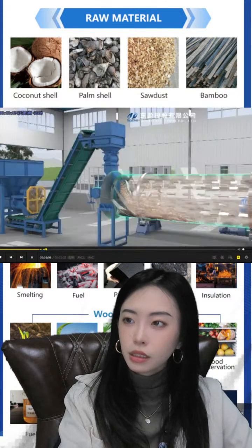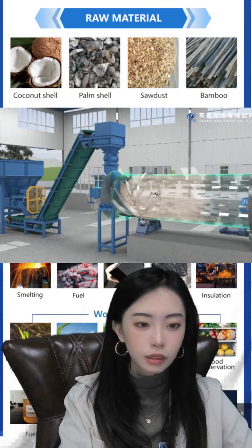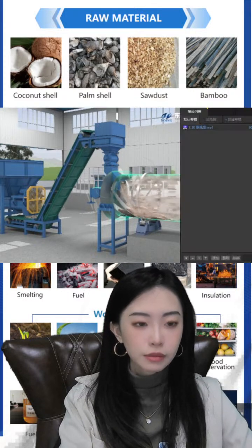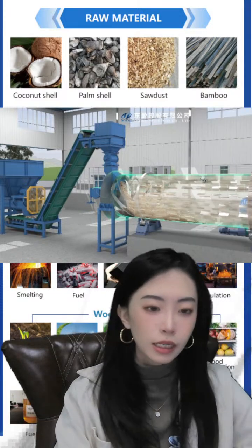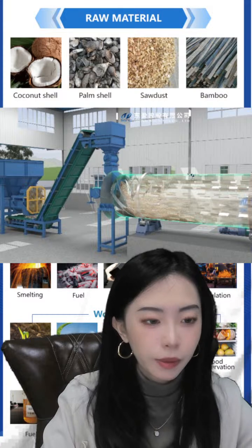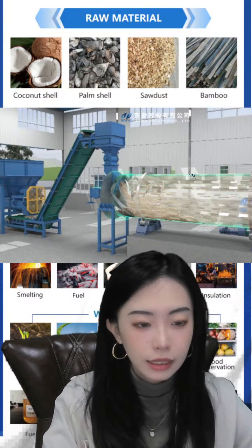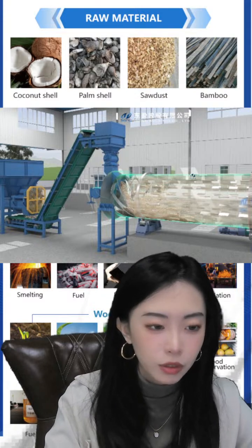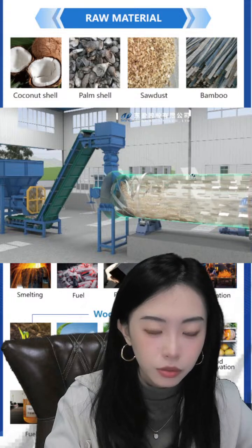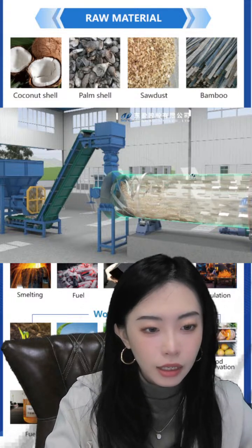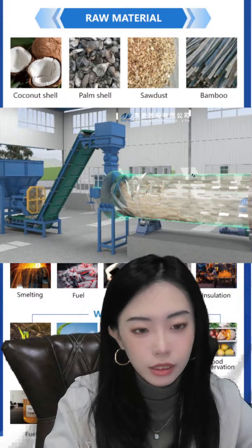You can see inside at the front of the dryer many spiral plates that make the materials go inside the furnace. And inside this dryer, there are many tipping boards to turn the material so that the material and the hot air come into full contact with each other, because some materials have a high humidity and will clump together.